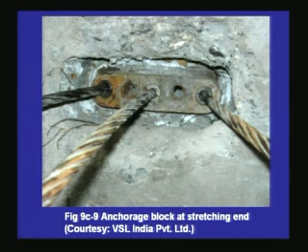After the stretching of the tendons, you can notice that they are anchored in the anchorage block. You can see the wedges that are holding the tendon in place, and this anchorage block is transferring the pre-stress from the tendons to the concrete.